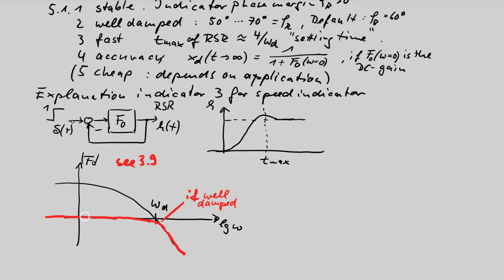So the closed loop Bode plot magnitude curve looks like this curve. And if we now compare this with known behaviors, then you can very easily see in the workbook page 16 that this fits to the PT2, red curve, fits to PT2 step response.